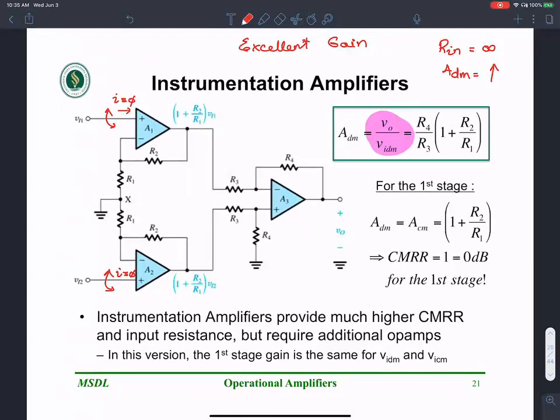Okay, I'm going backwards with the end in mind. So let's analyze this circuit. We see that this is connected to ground, okay? And because of virtual ground, this is going to be a voltage division, and we don't have to analyze this circuit. We know that this is a non-inverting amplifier. Remember, the input is applied on the positive terminal and tied back here through a pair of resistances. Okay, if you pay attention to this, that is exactly the same.